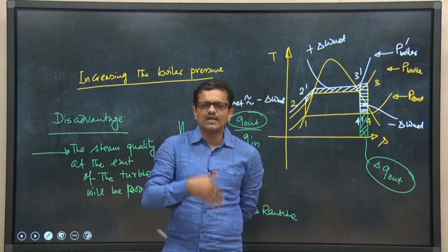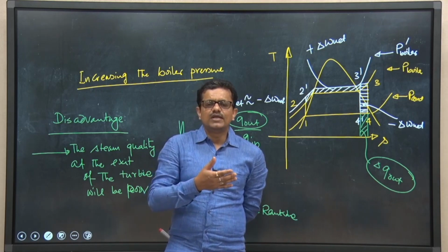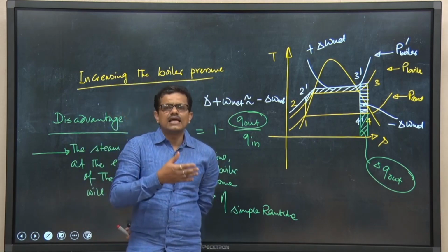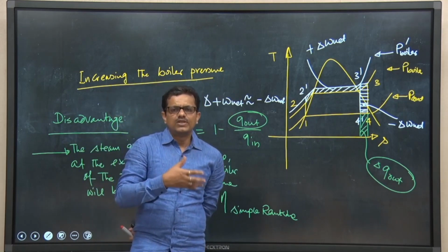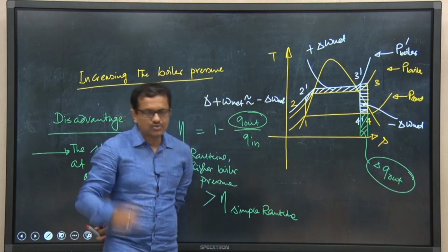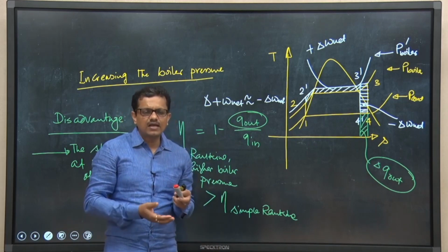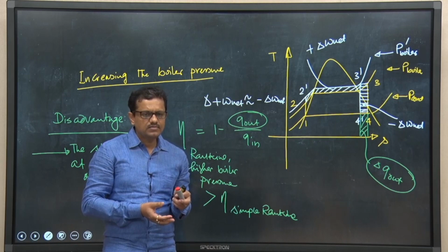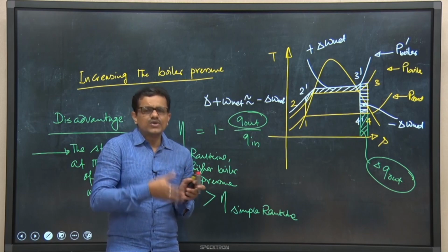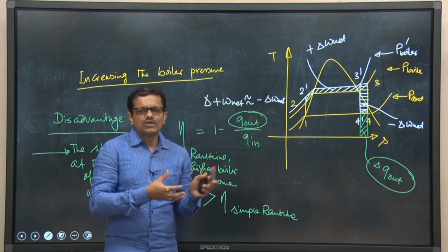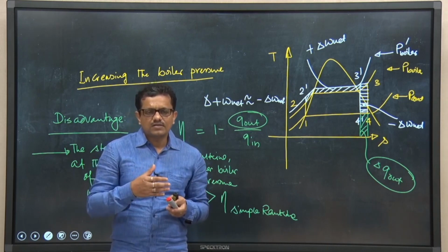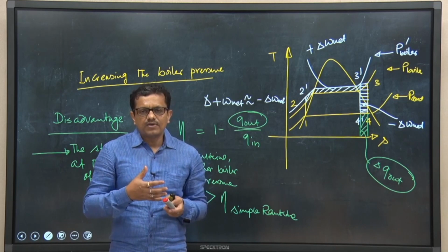If we need to go for superheating the steam, then again we need to consider the additional costs involved, the initial as well as the operational cost and operational issues. So, initial cost will be high as well as operational cost will be high. So, we can see that though we can increase efficiency, we are going to have several other problems. The reheat cycle offers an alternative.